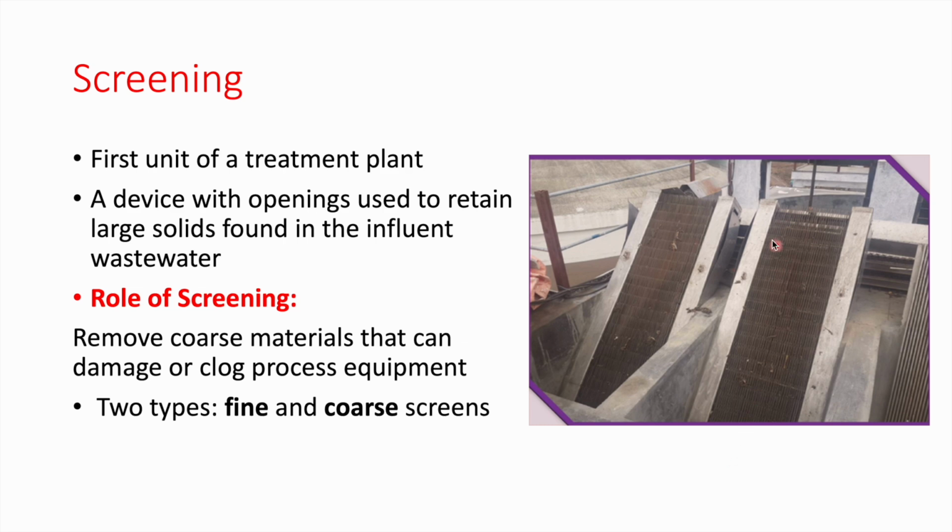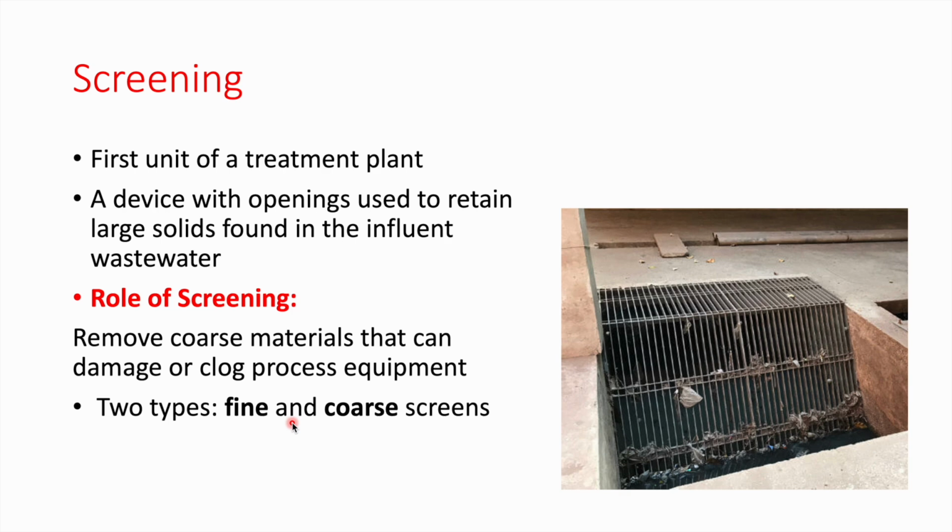They are motorized and not manual, to keep cleaning these bars, and they remove very small particles, and sometimes they can be used as a primary treatment. So we can sometimes consider the fine screening as the primary treatment. For small to medium scale projects, you can use the coarse screens. As you can see here, it is simply designed, placed in the inflow channel, and it can be manually cleaned